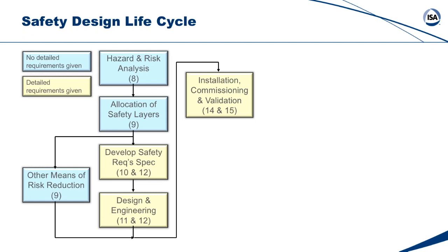And we want to make sure that the system meets the specification, that things have not inadvertently changed, potentially for the worse. Clause 13 you might see is missing. That's the factory acceptance test, which in the 2003 and 4 versions of the standard was informational, not an absolute requirement. But in the 2016 and 18 versions of the standard, Clause 13, the factory acceptance test is mandatory.